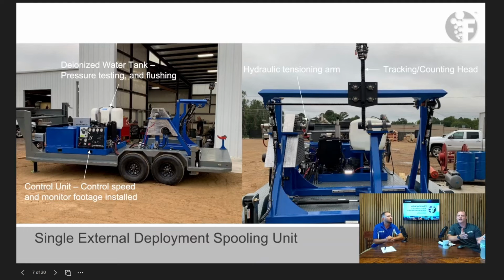That's good, because when you look at production tubing, we're talking barrels of capacity, and here you're talking gallons. And usually what do you put in that tank? Is that just deionized water? Deionized water. Yes, you need deionized water, because if you have regular water, it could react to your chemical, which can cause a plug.